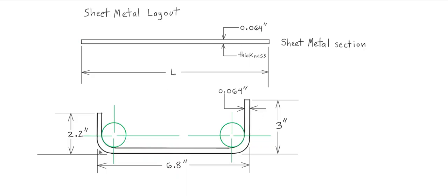So this has to be bent with a sheet metal brake without inducing any stress risers, right? So the easiest way to accomplish the correct sheet metal layout calculations is to first take the curve. Of course, we're working with a 90-degree bend, but take the curve with respect to a circle and place the crosshairs through it. So this, or these, will function as the bend tangent lines, one for the vertical y-axis and one for the horizontal x-axis.